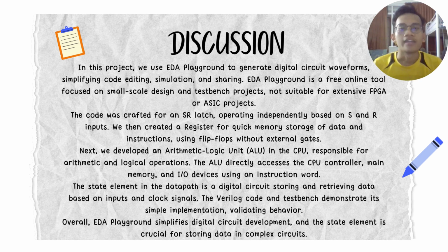Next, we developed an arithmetic logic unit, ALU, in the CPU, responsible for the arithmetic and logical operations. The ALU directly interacts with the CPU controller, main memory, and I/O devices using an instruction word. The state element in the data path is a digital circuit storing and retrieving data based on inputs and clock signals. The Verilog code and test bench demonstrate its simple implementation, validating behavior. Overall, EDA Playground simplifies digital circuit development, and the state element is crucial for storing data in circuits.